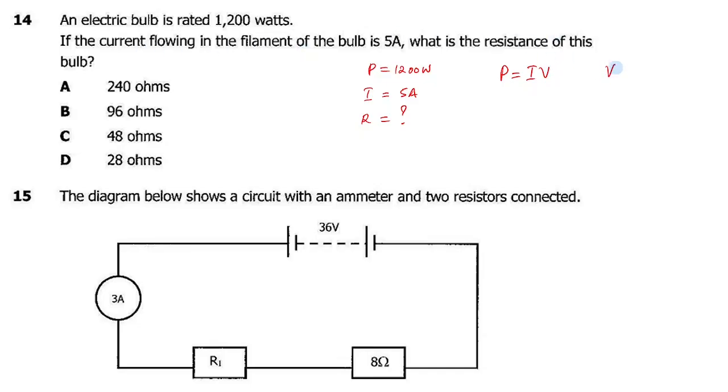So we know voltage is equal to current times resistor. All right. So we'll substitute where there's voltage, put I R. So power is equal to current times open brackets, voltage, or put I R. So we'll now simplify. I times I is I squared, then R. So this is the formula we are going to use. So power, we will make R the subject of the formula.